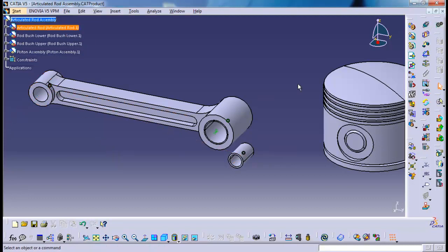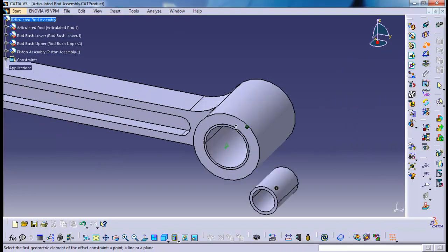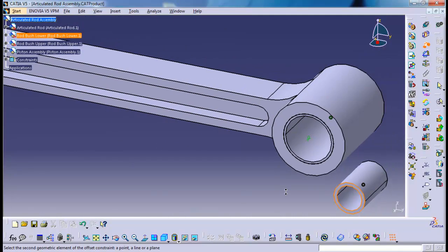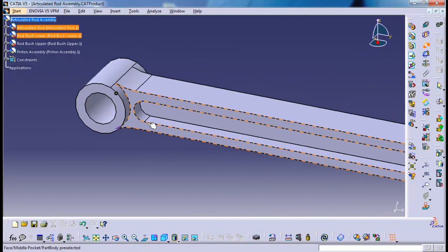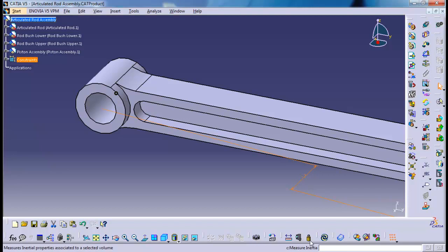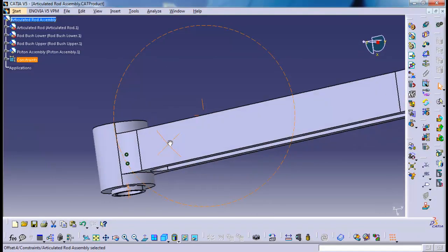Otherwise, there are too many options for the part to still meet that constraint, but be in the wrong position. As you can see, it is also important to be careful, as negative and positive offset constraints can easily be mixed up. You must always check your part.